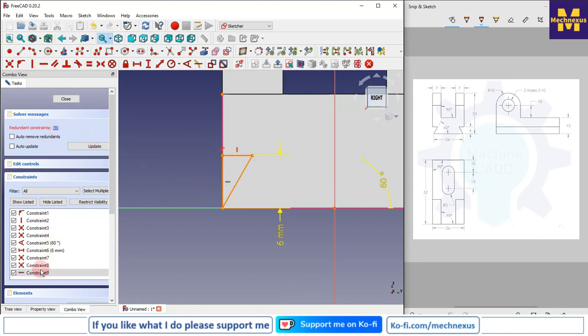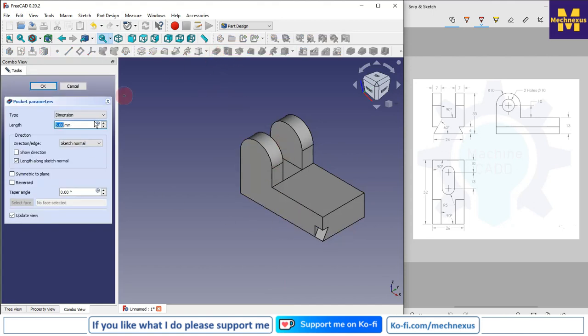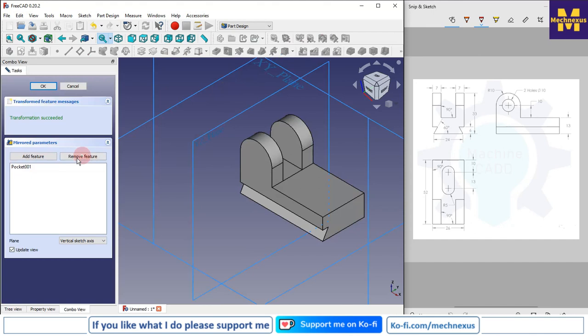Here is a conflict, so simply delete it. Now I will come out of my sketch and I will go for the cut, and I will simply say through all. Now I will go to the tree view, I will select my pocket and click on the mirror tool, and Pocket001 is selected.